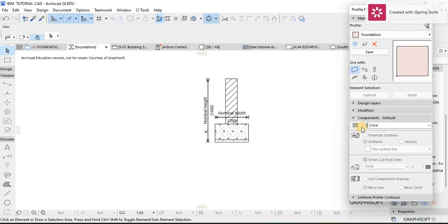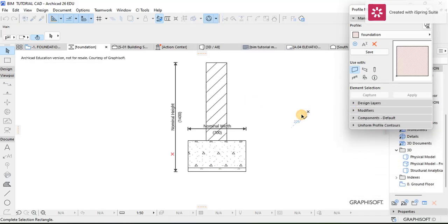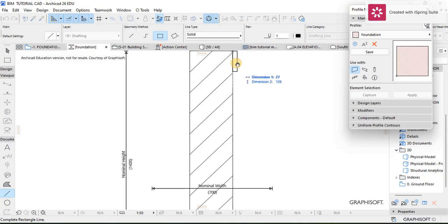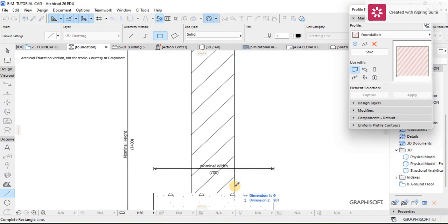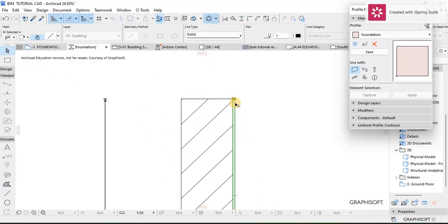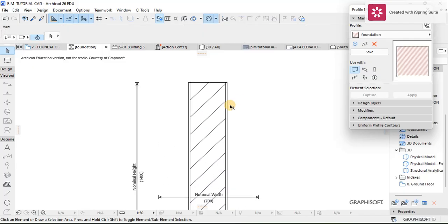So with that said, now we can look at how we can add some damp proofing onto our masonry block. To do that, we're going to have to make a small layer on each side of our masonry block. So I'm just going to draw a small layer there, and it's going to be a bit small, like 10, and then I'm going to press enter, and then take the same layer and drag another copy to the other side, for damp proofing needs. So that's what we have.